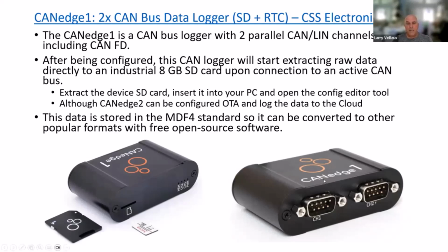It's got the memory to store the messages, 8 gigabits, but it can have up to 64 gigabits of memory. It's got an SD card, which is actually that memory that we just referred to. In this case, the only 2 ports it has are actually CAN ports, so there's really no way to connect it to your PC to program it. So this SD card functions as both the storage for the log messages, as well as you can plug it in your PC and use it to configure it.